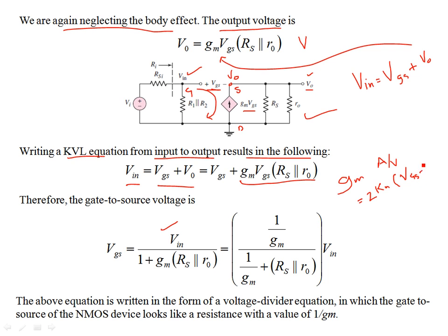So the idea is that what it means is that your input is volts and the output is current. Okay, the output is always the current. So that's why these MOSFET configurations are also known as transconductance amplifiers. Okay, so for example, if the input is VGS, the output is the current. Okay, the output is GM-VGS.